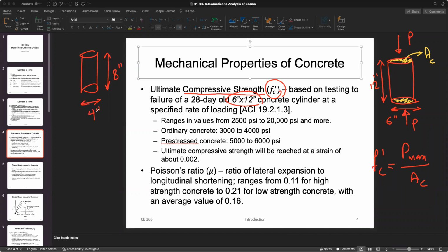To understand the compressive strength of concrete, usually we use 3 of these tests and make an average of 3 specimens. We break 3 of them, and then the average number would be the compressive strength.